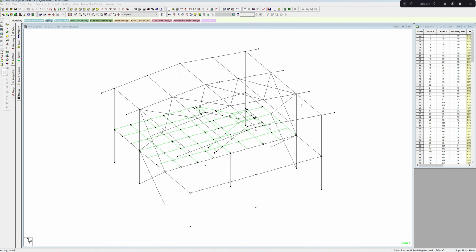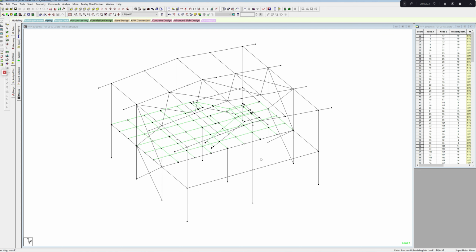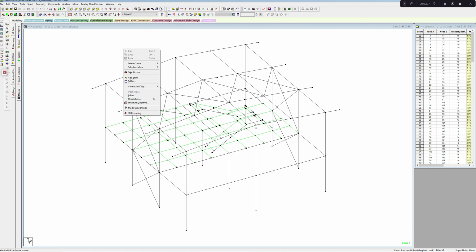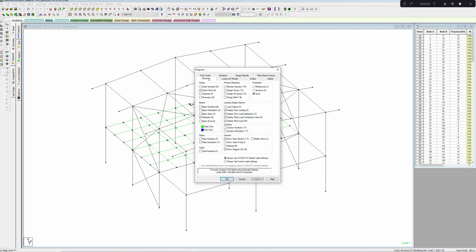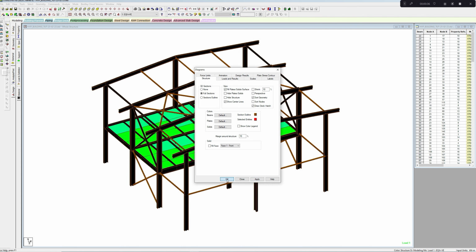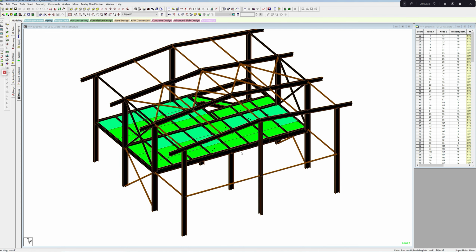In this section, we shall learn how to provide the cross-section elevation data to the structural general arrangement drawing detailer so that he is able to prepare the structural general arrangement drawing, that is called structural GA. So this is our STAAD file in which we are working. If you go to level, structure, full section, fill plates, apply, this kind of 3D view will appear.